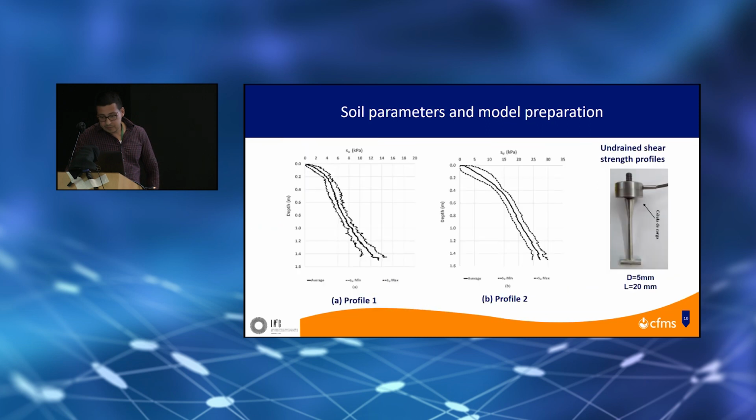So we'll move. Here we can observe some examples of the achieved undulating shear strength profiles measured by T-bar, and the test takes place in flight. So we can see the differences between the two profiles of the soft clay and the soft to stiff clay profile.